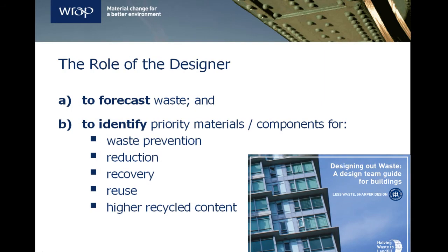The designer has an important role in forecasting the waste on a project and identifying the key opportunities for waste prevention, reduction, recovery and reuse, as well as opportunities to specify products with high recycled content. The definition of a project in the English Site Waste Management Plan regulations includes the design stage. Plans are required to include actions taken to prevent wastage prior to construction. Therefore, designers have an important role to play in site waste management planning.